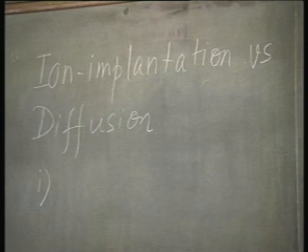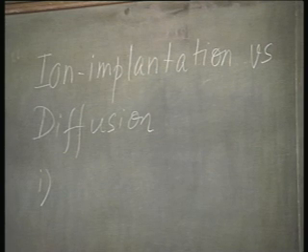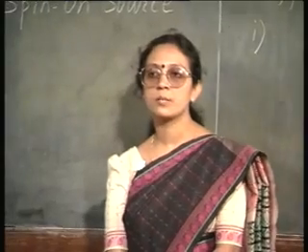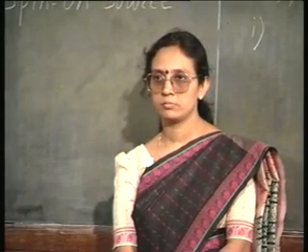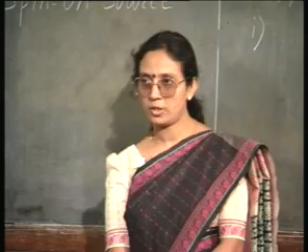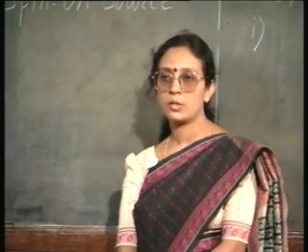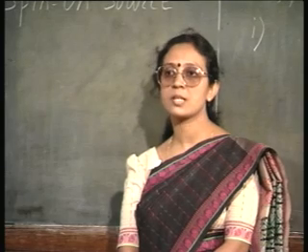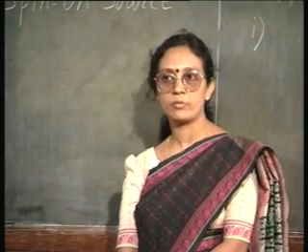In diffusion, one of the major considerations is contamination. That is to say, you cannot use the same furnace for diffusing, say, boron and phosphorus, right, because inside the furnace there will always be a lot of contamination. Like in a phosphorus diffusion furnace, inside you will have a lot of P2O5 deposition.